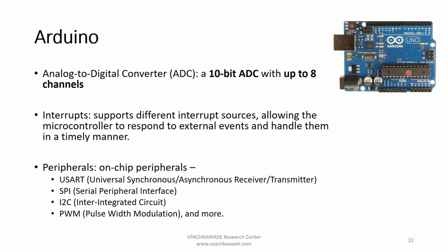Also inside the chip, we have interrupt sections which support us to perform some operation when there is an interrupt request. Let's say the microcontroller is busy with some operation, let's say a logic or arithmetic operation, and from an external peripheral, it receives a request.